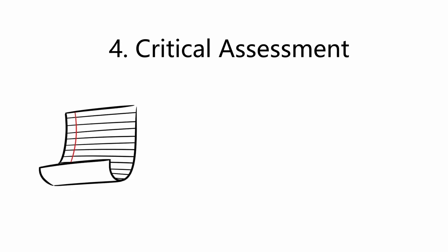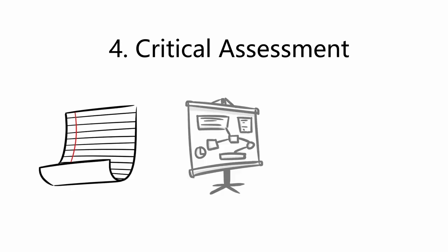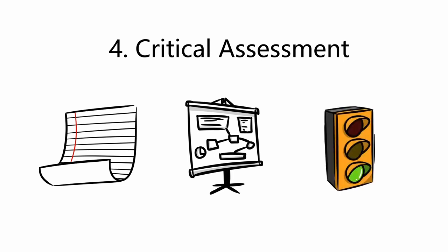Step 4. Critical assessment. Produce a list of all components of the relevant machines. Discuss and understand the role of each component and their interdependencies. Not superficially, but in detail. Discuss the optimal conditions for the operation of each critical component, e.g., temperature, lubrication, cleanliness, sharpness. Then define the normal operating conditions.